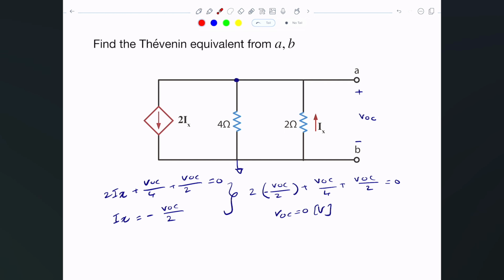Okay, so let's find the value of that resistance. Which method? We can try method 1. However, method 1 tells us you have to turn off all the independent sources. I don't have independent sources, I have a dependent source, so I can't turn it off. So I can't use method 1. How about method 2? Technically you can't use it because you have to have either independent sources alone, or a mixture of independent and dependent sources, and I'll show you why now.